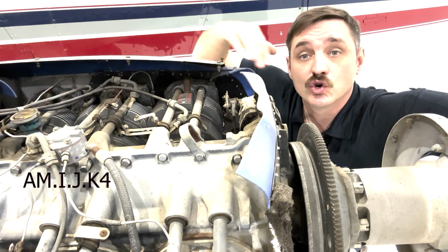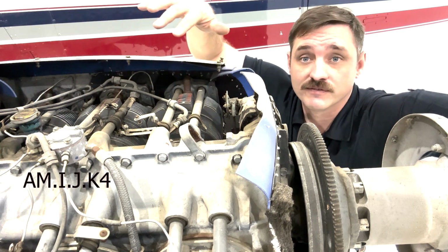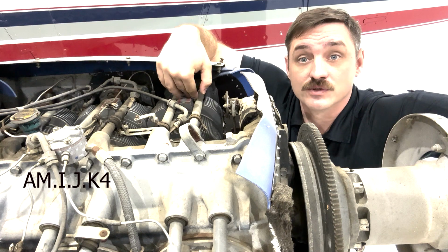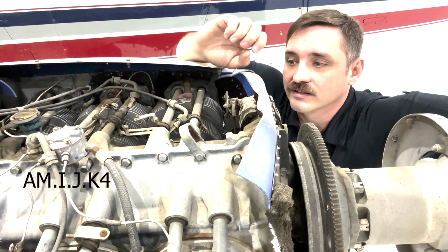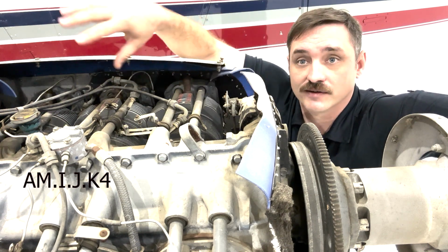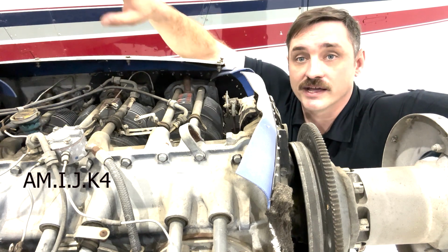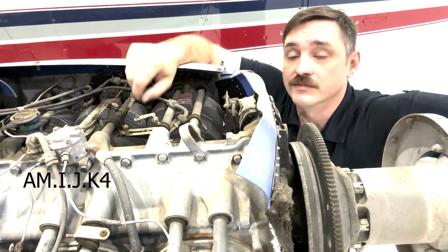And the way that we cool a reciprocating engine like this is through convection, and through radiation, as the jug radiates heat through these cooling fins. Hear that? The convection happens, and the air, as the engine travels through the atmosphere, grabs the heat and moves it away, lowering the overall temperature of the engine.